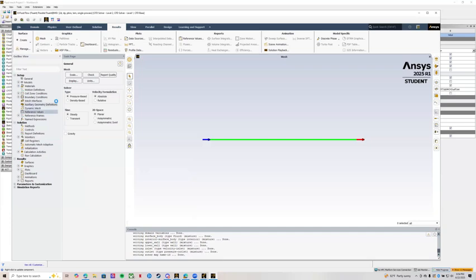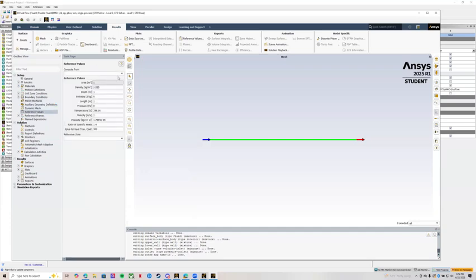Next, we've got to go to our reference value tab. This is where we're going to reference all the values for everything when we do the initialization. So we're going to go from our inlet, and notice how everything goes to the dimensions and values we put in. Well, it's not going to go the exact thing, but you want to make sure it's from the inlet to surface body. This will make sure that we're going to go from here to over here. So once we're done with that, we can go down to initialization.